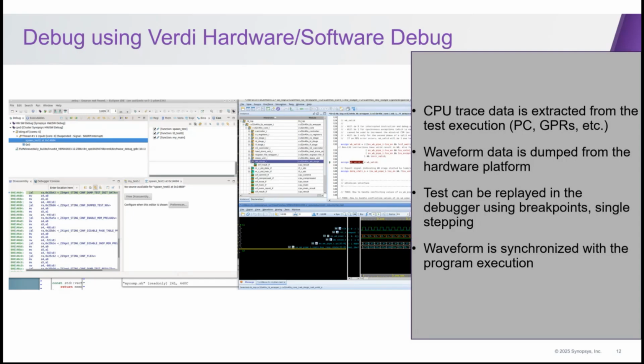They set a breakpoint on a function or on one of the instructions, they look at the registers, and they run it step by step. They look at the registers to see if these are the expected results. When I developed some tests before for ARM coherence, I did something similar. That's how software engineers look at debugging a case.